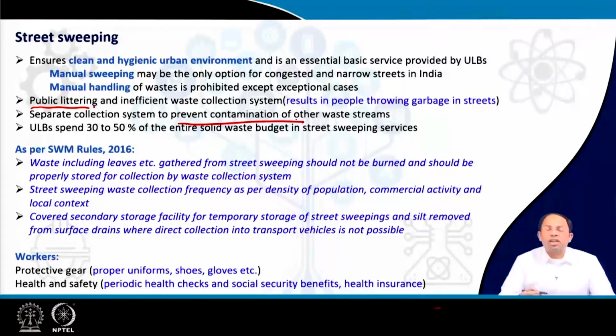And sometimes street sweeping is not done alone. That means drains which are not that deep, shallow drains, are also cleaned along with the street sweeping service. So the silt from the drains, or the sewage, or the sludge from the drains also gets mixed with the waste, which may contain pathogens. So it's better to keep this waste stream totally separate from the other municipal waste streams.